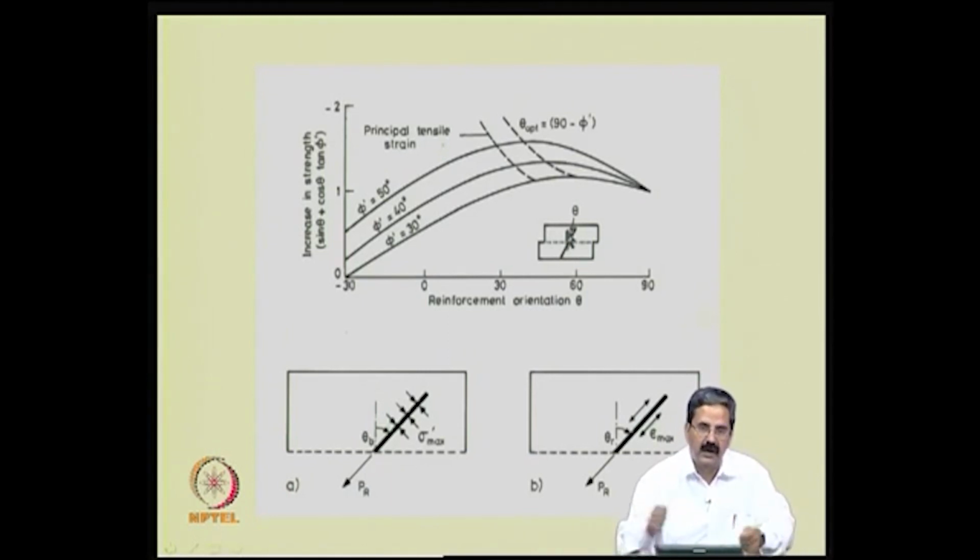You do not need to really do something else to get these angles. Because the moment you apply load, the failure surfaces develop like this, you are just putting a geogrid, and if you really understand what could be the probable failure surface and what could be the angle, it will be in this range, and definitely you can be very sure that it is going to be effective.